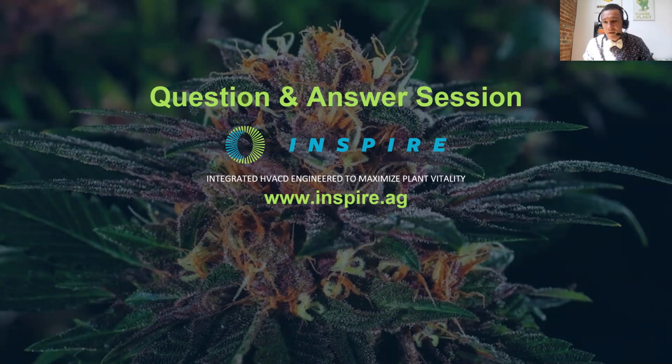So maybe it's about getting a water test and understanding what's in your water as it comes in. Just like Rob said, as you recycle it, let's learn about the microbes that are in there. Let's make sure that we remediate with UV filtration or some sort of treatment, ozone treatment or something in the water, and then have a secondary process to make sure that we're not putting ozone and UV into the root zone. But absolutely, there's some spot fixes that people do. I think a lot of people like to run systemic microbes, get as many fungal and bacterial colonies on and in the plant as possible so they can prevent the uptake of that, so they can filter that horrid water as it comes into the root zone.